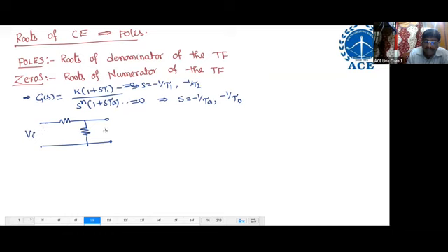So Vi, V0. What is the time? What is the pole here? How many poles are there? How many zeros are there? Find the transfer function. V0 of s by Vi of s equals what? R2 by R1 plus R2. That means there is no time constant. It is a constant only. What is the order? Zero order. There is no pole, no zero.